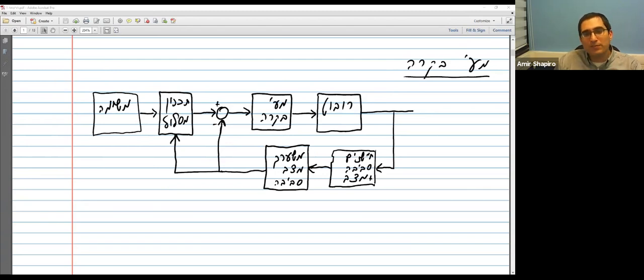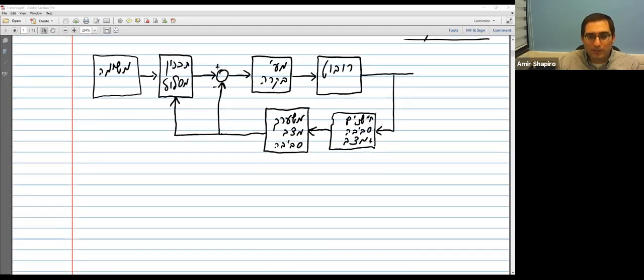You have to take something from one point and put it in another point. So you have a mission planner on top of it. So we actually have three levels. The lower level is the control level. The middle level is motion planning. And the upper level is the mission planning. This is how we plan a control system of a robot.